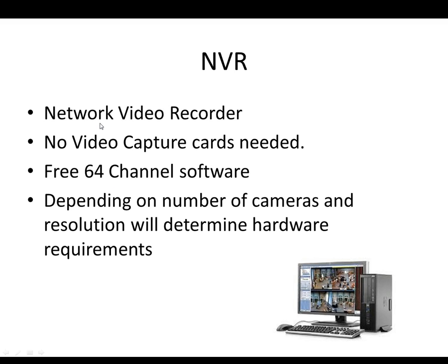And how the cameras record or are used for live viewing is we use an NVR, which is a network video recorder. It is different from DVRs in the sense that it doesn't need any video capture cards. It is purely software. We do provide a free 64-channel software, so depending on the number of cameras and resolution will determine your hardware requirements.